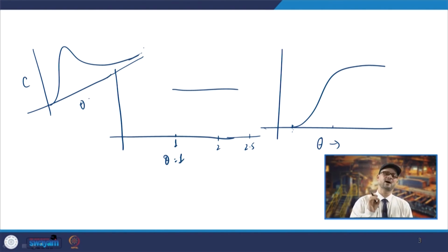It means that some part is staying a very long time inside the tundish. So, we have a certain region where if the metal goes from there, it takes a long time to come out of it. Apart from this plug flow, which will talk about the plug volume, and mixed flow, which we will study later, representing the mixed volume inside the tundish, you will have another zone, the dead zone.